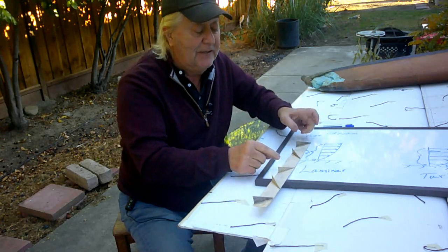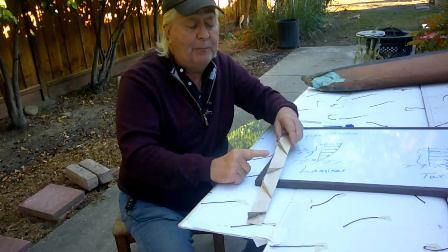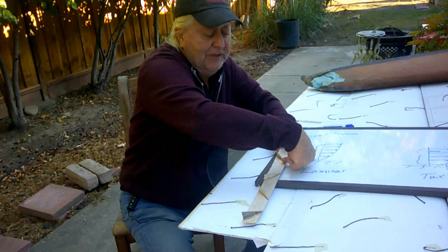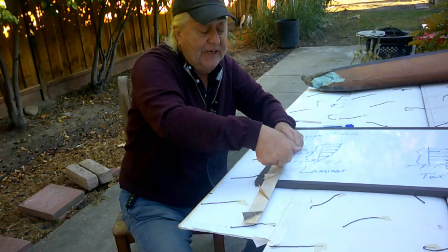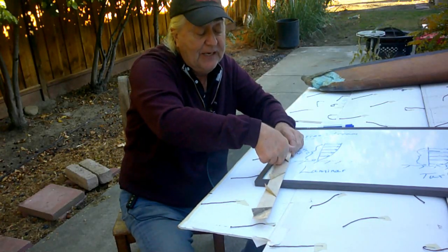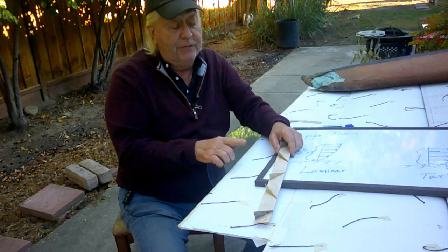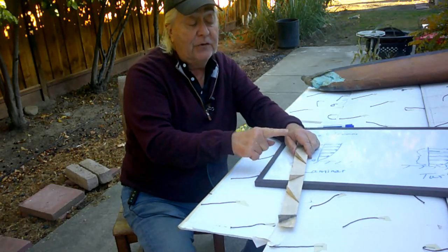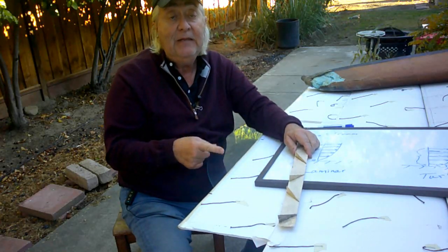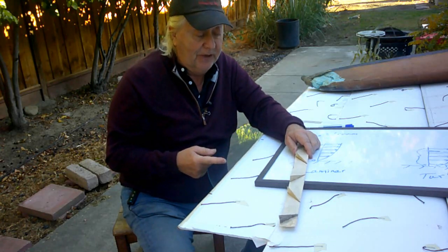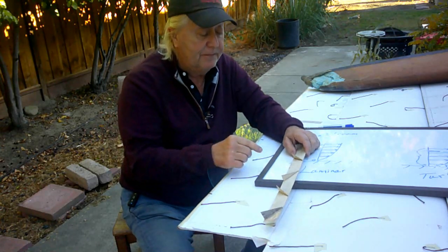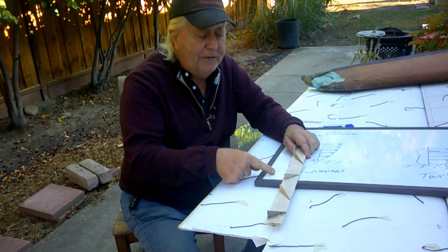And what happens is you get flow separating behind this wall. So as the flow comes in this way, it doesn't turn and stay attached. It tries to turn, separates, and rolls into a vortex. And that's the trick to these. It rolls into a vortex this way, in the direction that the flow is already going. That's a good thing. And you get one off of this side.